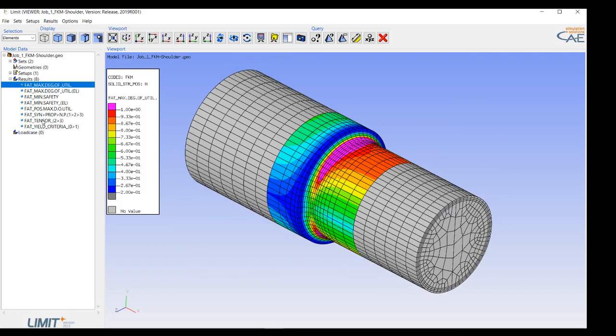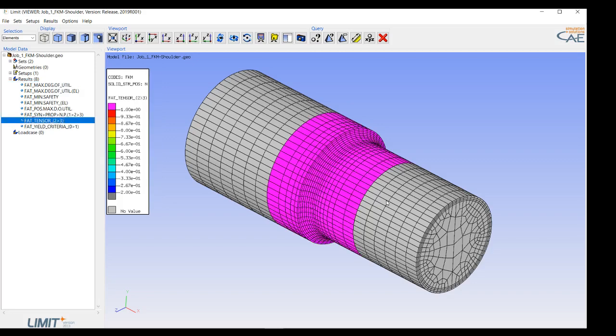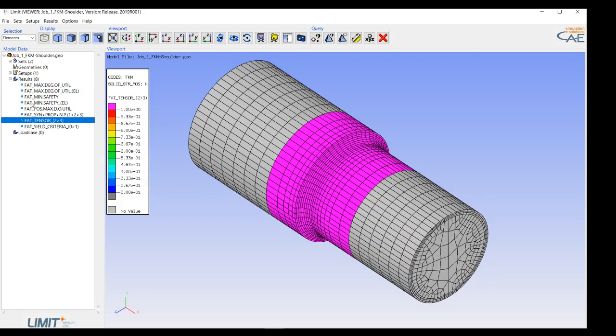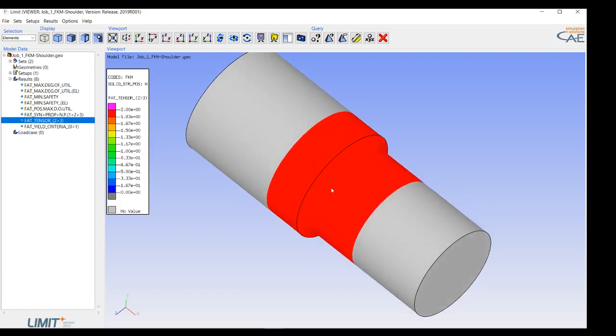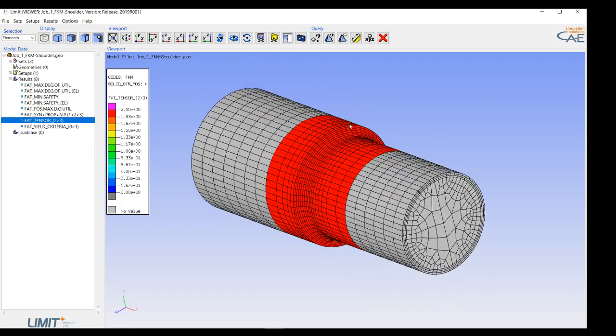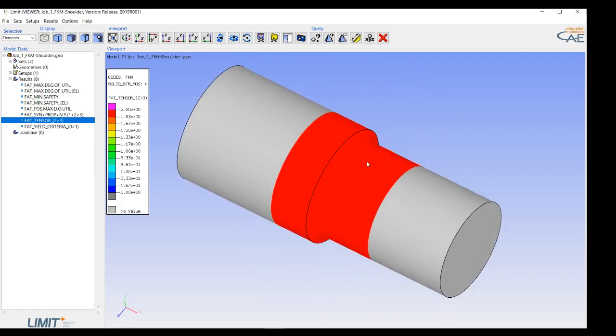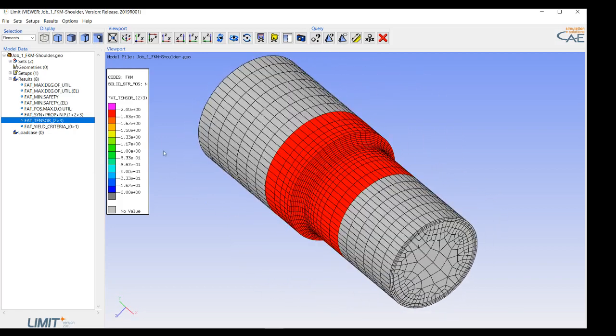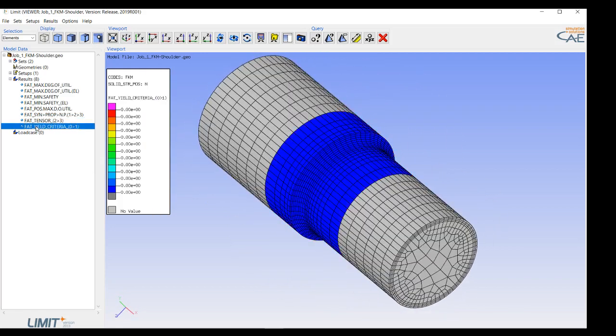Here we can take a look if the reduction to a 2D surface tensor was successful. So a value of 2 throughout the structure means that we have a 2D surface representation, which is correct.